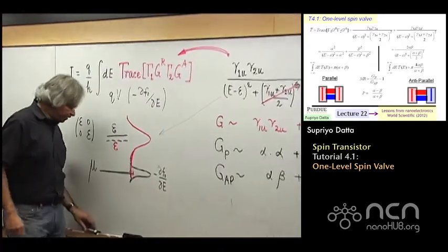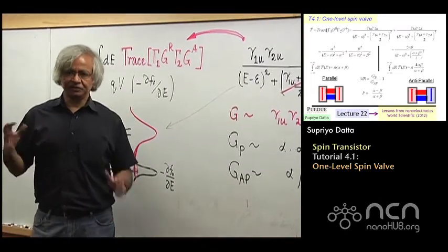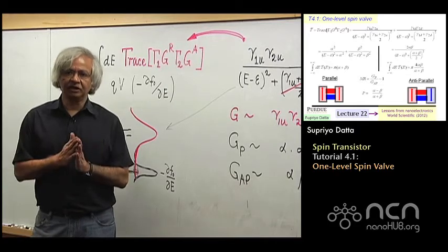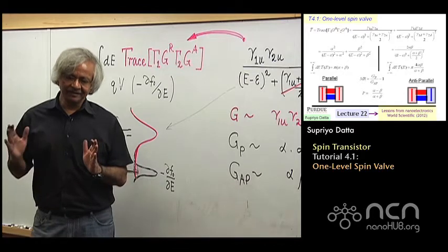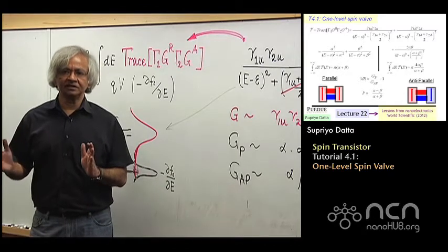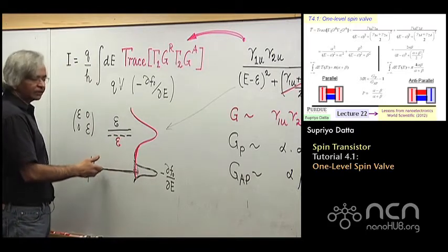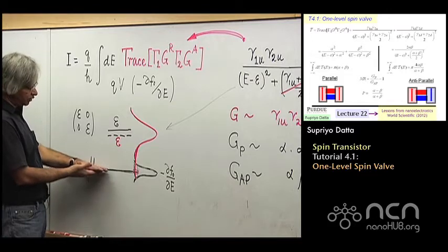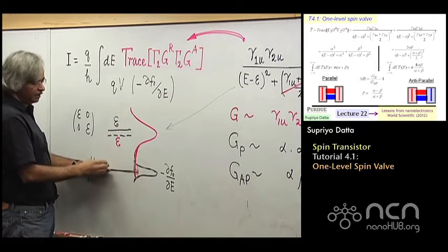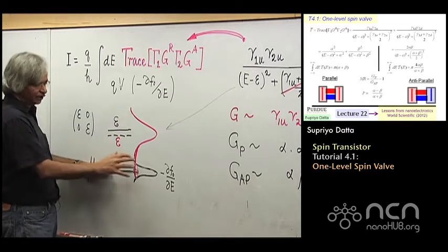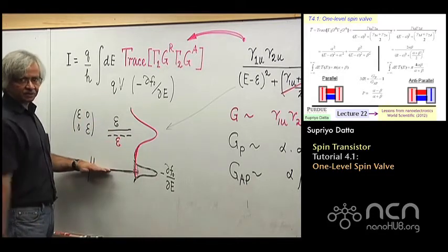As I said, the field of spin valves started with the GMR devices, where the channel was actually a conductor, where electrons flowed in the conventional way through the channel. Whereas nowadays, what is used a lot is these magnetic tunnel junctions, where the channel is actually a region where electrons tunnel through. In the sense that we are talking about electrons with an energy which is way below where we assume the energy level to be. And the reason it can get through is this tunneling process. And in tunneling junctions, that's the expression.